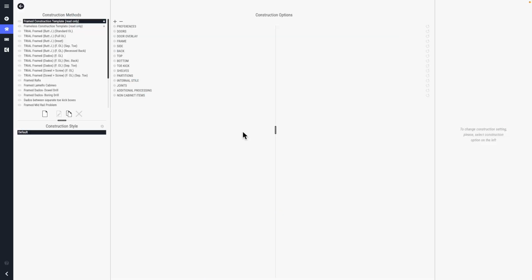The final project we will check in this video will be the edge correction, which is relevant specifically just for CNC users. Now, sometimes you come across cuts that have inside corners, especially with pocket operations. And these inside corners generate extra material due to the nature of the CNC cutting. And you can now assign a smaller tool bit to minimize these inside corners without cutting into usable edges. This is relevant to door profiles, door pockets, and certain other connection methods.